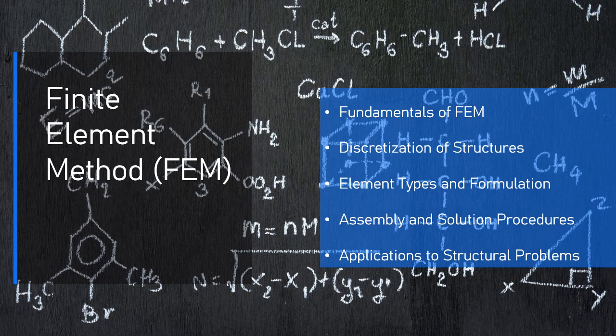2. Deformation visualization. The displacements are used to compute the deformed shape of the structure. Often, the results are displayed in graphical form, where the deformed shape is shown, often exaggerated to highlight the displacement magnitudes. This provides valuable insight into how the structure behaves under loading. 3. Checking for structural integrity.